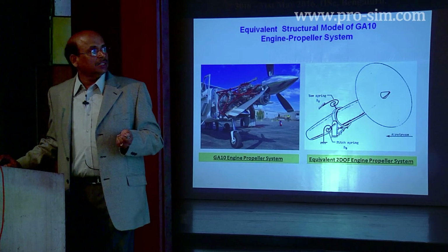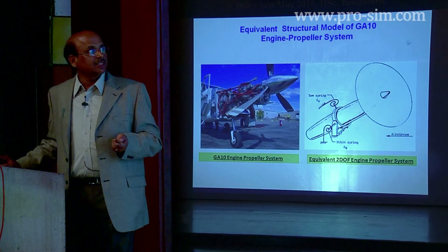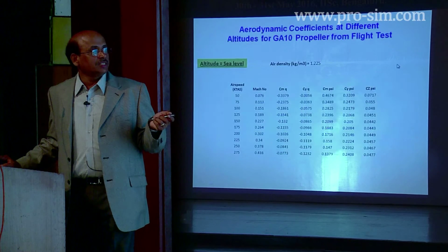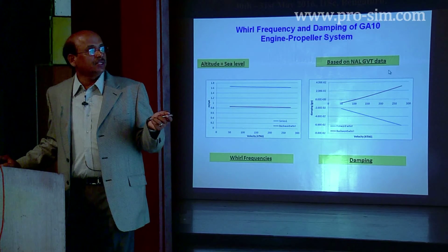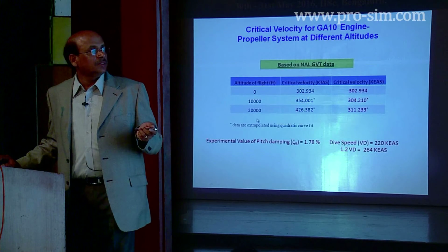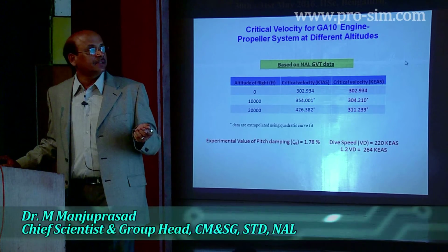Here the propeller part also was instrumented to capture the eigenvalues and eigenvectors. Based upon that, all the calculations were done, and we plotted again the VG-VF plots, based upon which we looked at the flutter characteristics and cleared it.